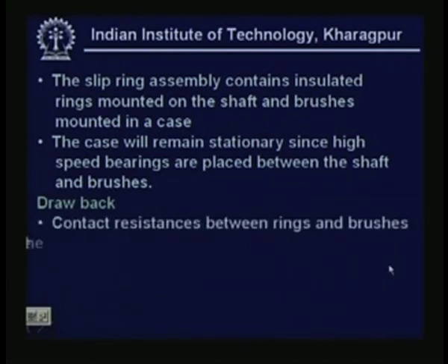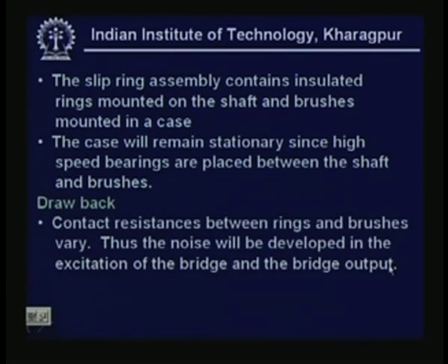The drawback, as I told you earlier, is that the contact resistance between the rings and the brushes varies, so noise will be developed in the excitation of the bridge and in the bridge output. We are not taking only the bridge output; even your excitation voltage will contain noise, even though you are giving a supply from a battery.